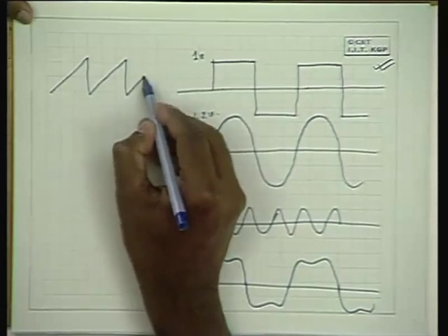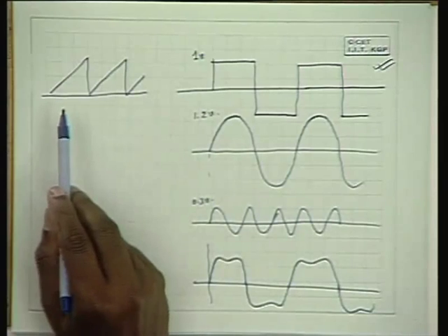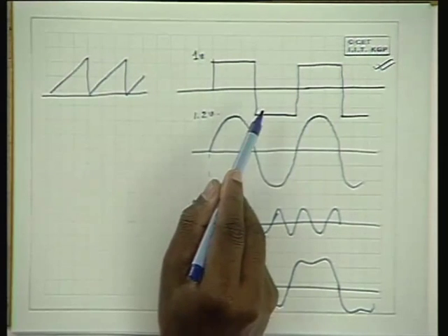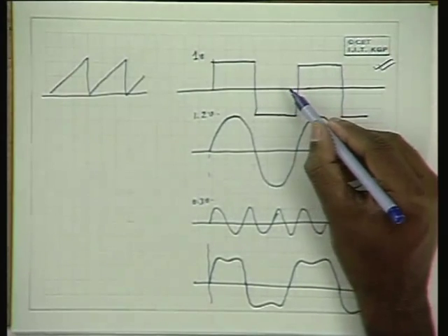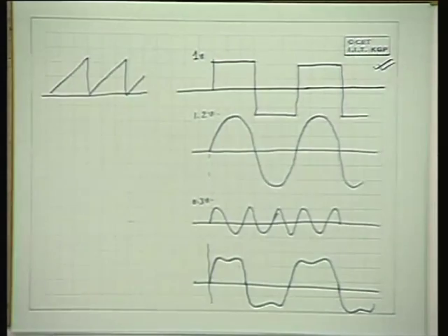On the other hand, you take a ramp signal of this type. It does not have this kind of symmetry, and you need all harmonics there: even the fundamental, second harmonic, third harmonic, and so on. If this signal is a sinusoid itself, how many harmonics does it have? Only one harmonic, so all other harmonics would be 0. So it naturally depends on the shape, the nature of the input signal. Okay.